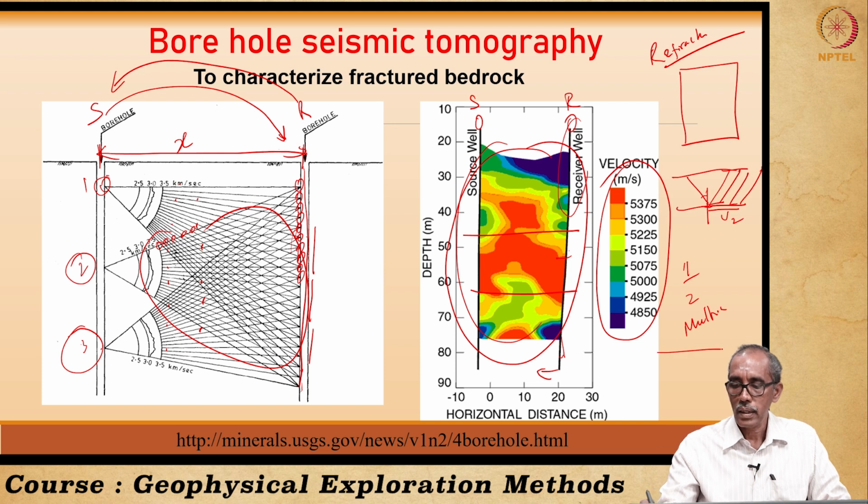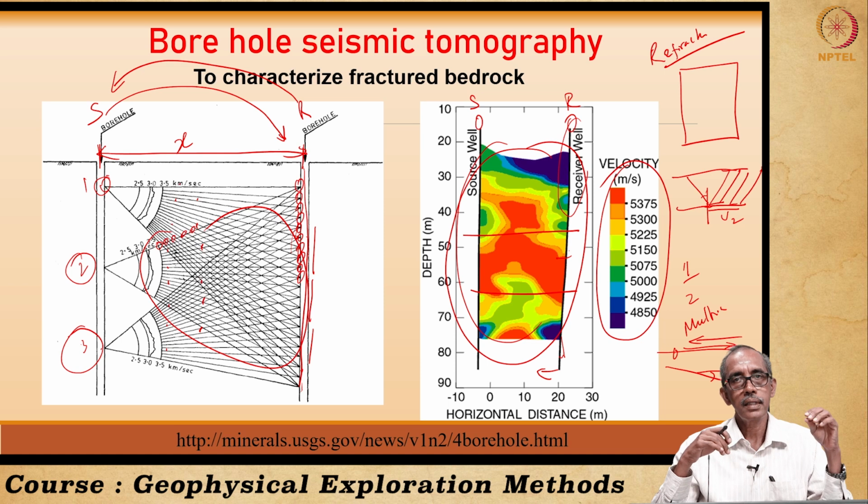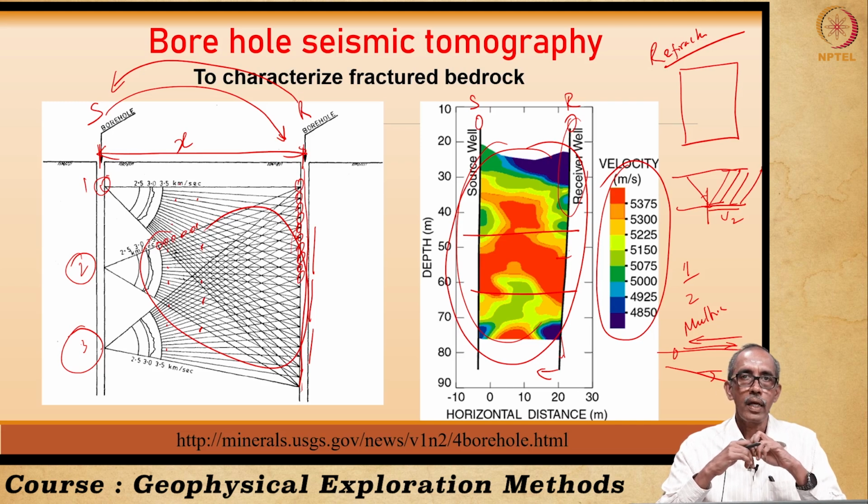And if the formation is inclined, that is dipping, we can determine the dip angle also. How? By carrying out shooting from down dip and then another shooting from up dip side. Using this time difference, we can estimate the angle of dip. Then we had a look into what are all the different arrangement of shooting, such as profile shooting, fan shooting and arc shooting. Then we had a look into some applications of seismic refraction method.